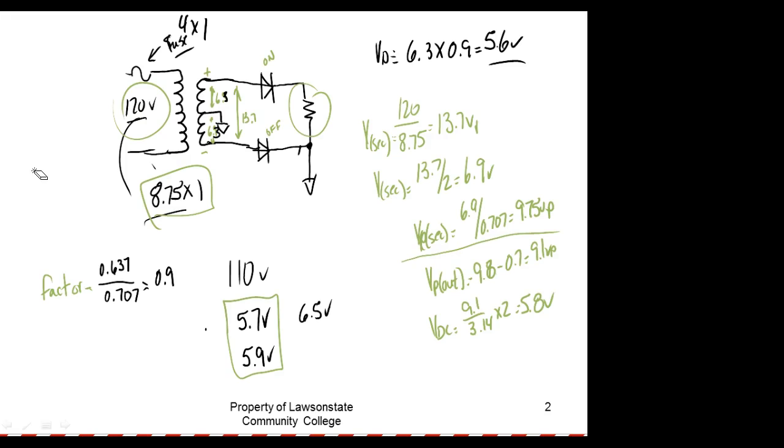You understand that? So if they short in the secondary, that means we get fewer turns in the secondary, so you won't get near as much voltage out of it. And of course, there's not really much you can do except take the dang thing apart. It's not easy to break that E apart and rewire it. So normally we consider transformers to be consumable. We don't repair them.